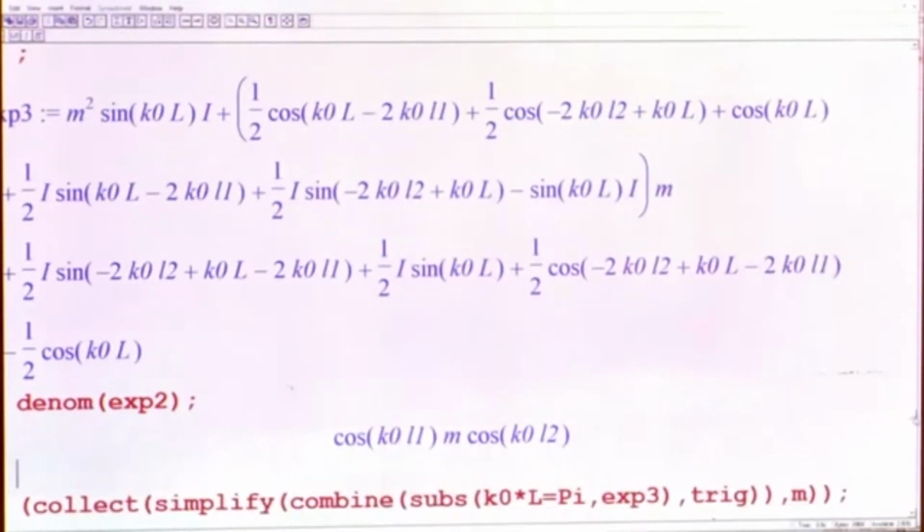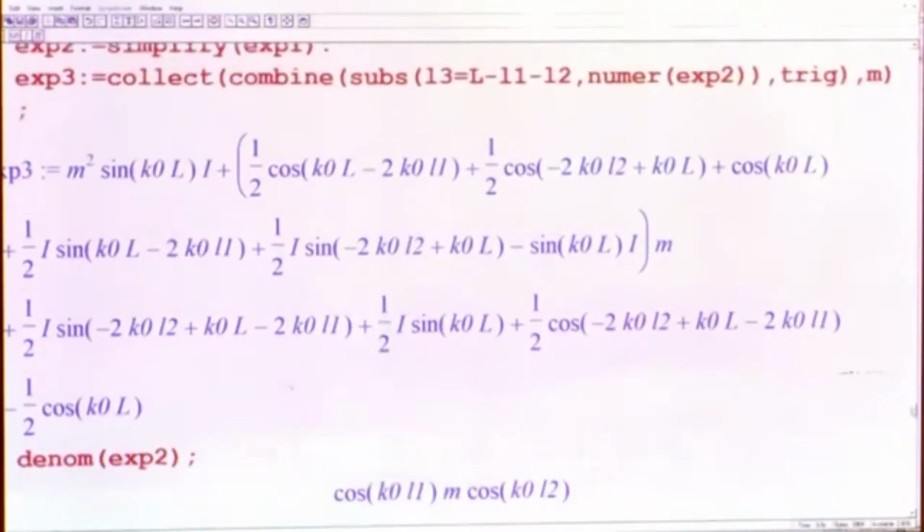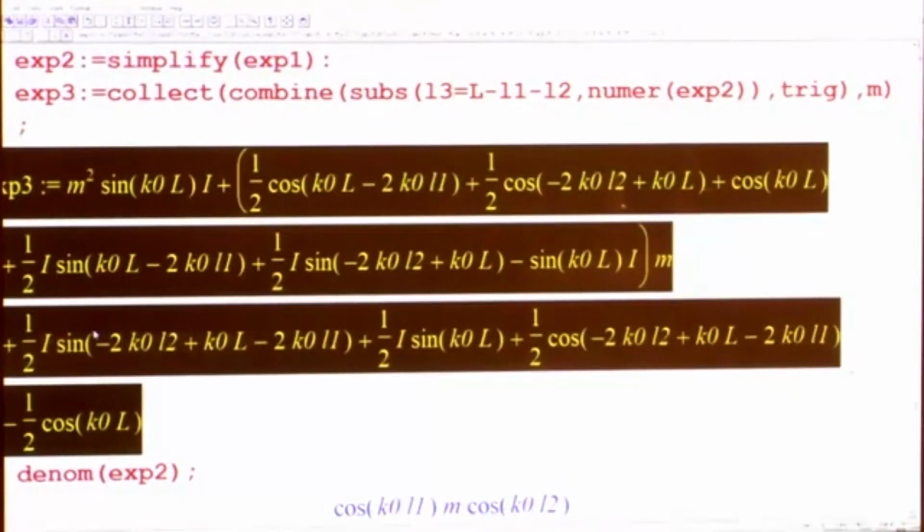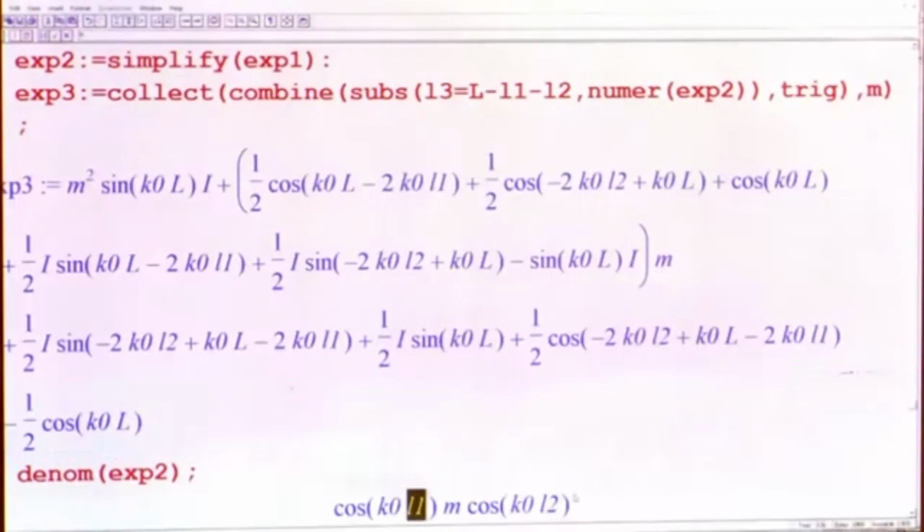All this while I was saying that by setting the impedance to 0 at the interface of the extended inlet and chamber junction, and the extended outlet and chamber junction, we can get the resonance of the annular cavities, and that is where the peaks will occur based on the plane wave limit. Why is that? Because this transmission loss argument consists of this entire big expression divided by the denominator. So, when the denominator goes to 0, that is cos k naught L 1 is equal to 0, we are getting the peaks due to the first annular cavity, that is the peaks due to the extensions at the inlet.